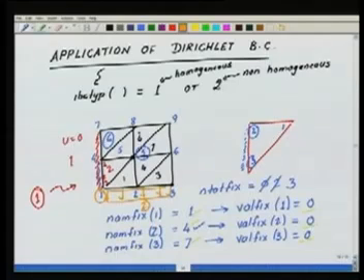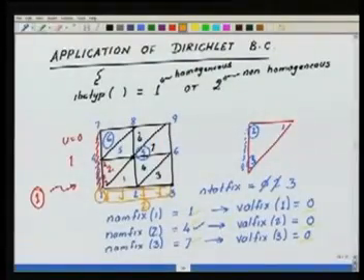When we say that we are going to fix the u on an edge, that forces us to fix the value of degree of freedom 1. In this case, the value of degree of freedom 1 is actually equal to 0. So the Dirichlet condition actually predominates over the Neumann condition. That is, if the value of the degree of freedom is fixed from one side, then that is what we are going to assign to that particular degree of freedom.